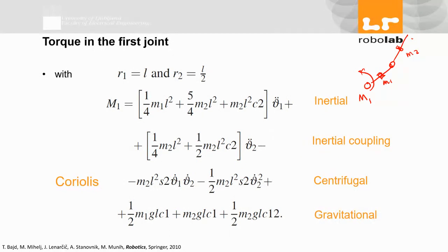So we have these two. We have two other components. The other one is centrifugal. Again, similar to what I said, since this is a rotational movement, we have an R joint here, and we have an R joint here. Specifically this one, when it's moving, because these are moving on a circle, you need centrifugal force, which is translated to torque here for us.